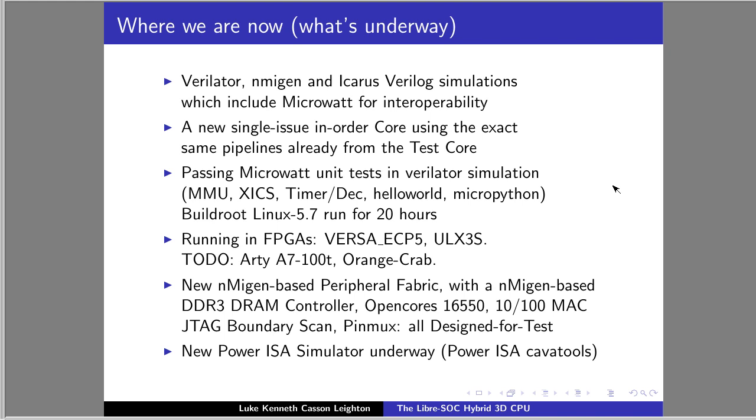I would like to create this fabric where we can auto-generate, just like in Earl Grey, which was inspired by the work that I did for IIT Madras, the device tree file, the documentation, the technical reference manual, and the Linux kernel header files, so you do not have to go and write those. And you'll find that part of this is already done in LiteX, but it's done in a way that, because it uses nMigen and it uses wildcard imports, it's almost impossible for anybody to understand except for the actual developers who created it.